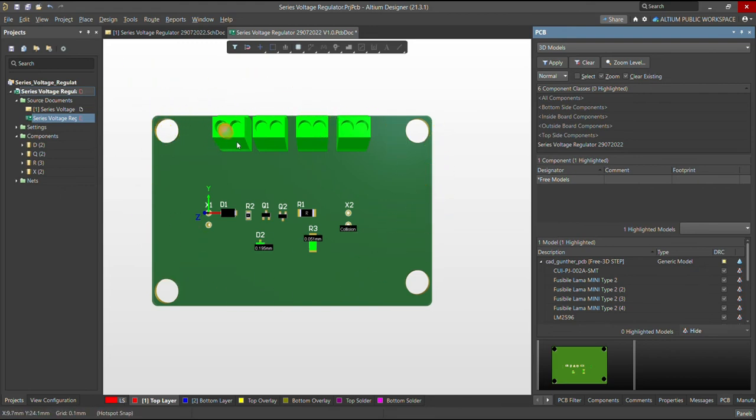But in your case, if you have got the PCB data from your mechanical department, then there must be some mechanical components which are necessary. So you have to make sure that your electronic parts do not have any kind of collision with your mechanical step data. Yeah. So let me first disable all these parts except the PCB.